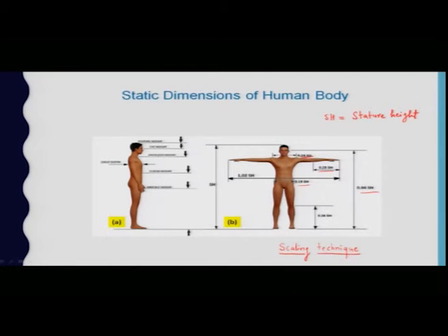So, this particular scaling technique is used when designing for users whose anthropometry is unknown. So, for example, a group of workers known to differ from the general population for some reason. For those, the scaling technique is helpful in evaluating the dimensions for designing a product. So, this is the most general condition where every height and every length is predicted on the basis of this stature height.